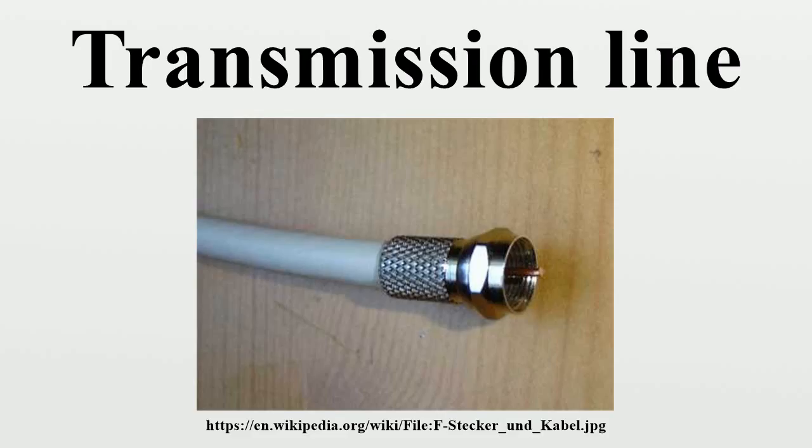That is, the voltage on the wire at a given time can be assumed to be the same at all points. However, when the voltage changes in a time interval comparable to the time it takes for the signal to travel down the wire, the length becomes important and the wire must be treated as a transmission line.